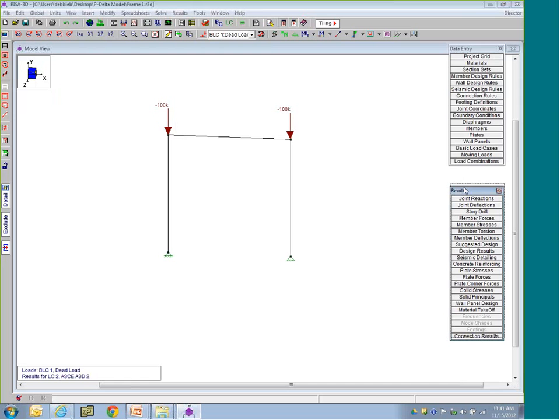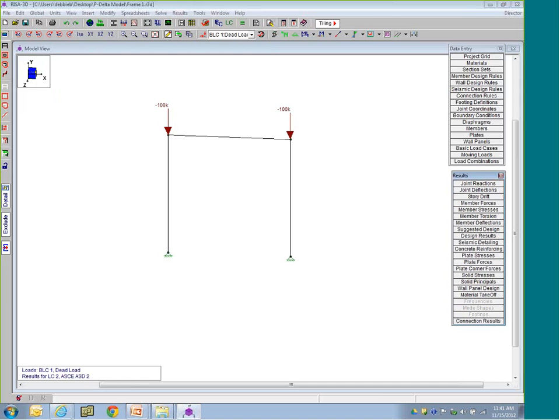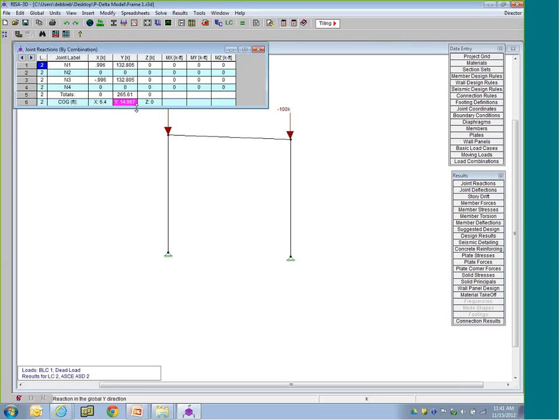The last step before you do that, since we put in a fake boundary condition, let's just make sure that there are no actual loads or reactions in the Z direction. And we can confirm that in the joint reaction spreadsheet. We see all zeros. So that makes us feel like, okay, I didn't do something incorrect. I can see that is correct. Okay, so now we are past that instability.